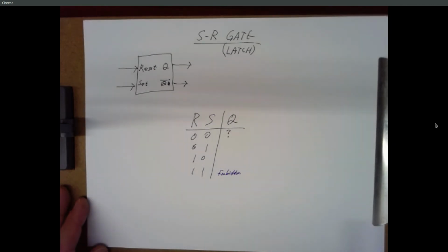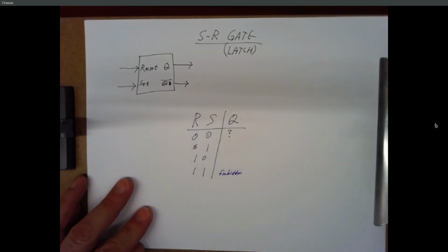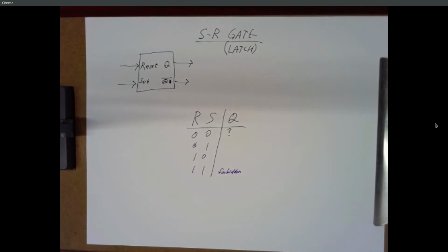It's possible, if everything lines up exactly right, that when you first power it on, it could be unstable. But chances are it's going to just start off as either a 0 or a 1. Turn the power supply off, turn it back on, and it might come up as something opposite. So it's unpredictable. But once it's got a particular value, it'll hold that value.